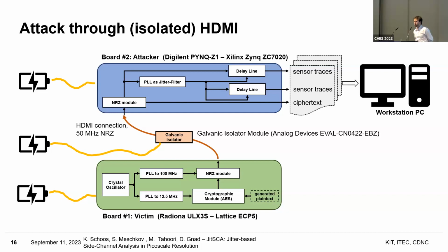Here we have a not that high speed victim, but we have a high speed sensor. What we are working with is actually the natural delays of this delay line inside the FPGA. With the current setup, we are limited by this delay line. As you've seen in the last talk, there is a possibility to improve that. I don't know what the limits are, but then we can possibly also make faster time samples, and by that, we can also sample faster communication signals.